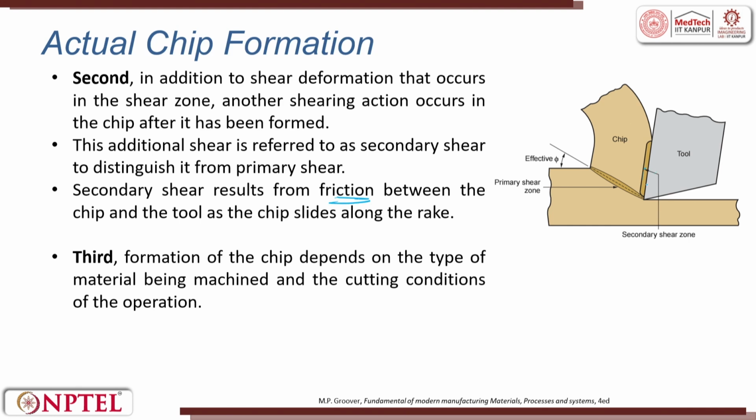and that is why we try to have a discontinuity here. When we have a discontinuity on the tool, it is called a chip breaker. This chip breaker tries to shear off the secondary deformation zone, leading to a discontinuous chip.